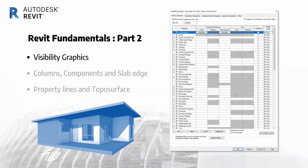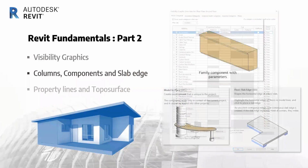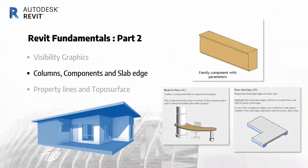Today, in Revit Fundamentals Part 2, we will continue using the Revit granny flat model from Part 1 and add a veranda, and then go and create some model views and use the visibility graphic tool to control what is displayed in each view. Next, we will be adding a model in place component for the kitchen bench, and we'll also look at creating a family for that kitchen bench, a family component, that is.